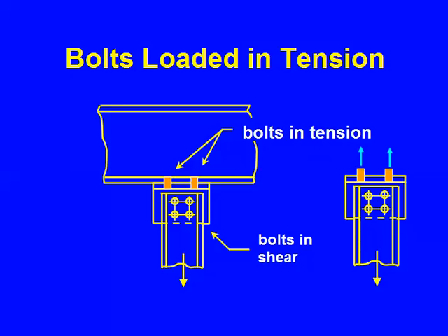So those bolts are in shear. You either know that or you draw the free body diagrams. And those bolts are in tension. Let's draw the free body diagram that corresponds to that. As I said a few moments ago, which free body diagram? The one that gets us the answer that we want. We want the forces in the bolts that connect the T to the lower flange of the beam. So we pass a cutting plane through there, through that intersection, and now we'll see it come into play.